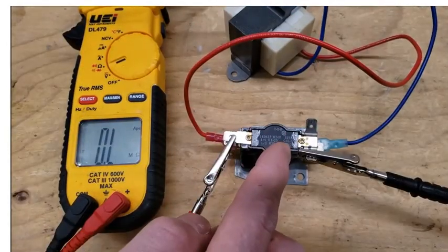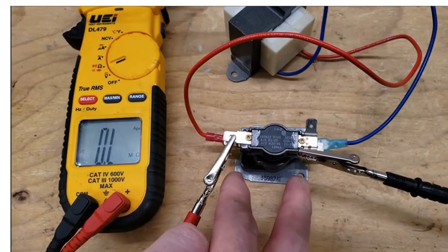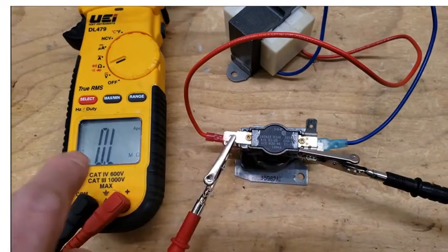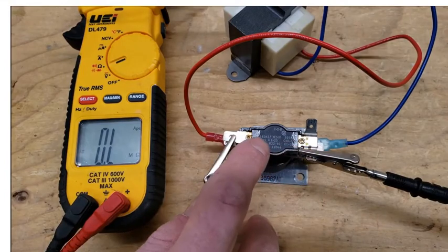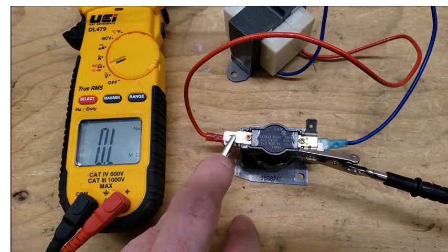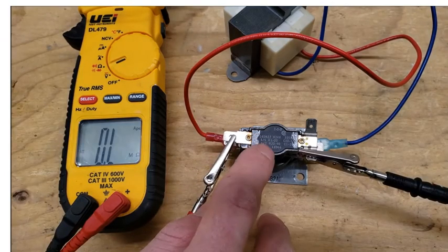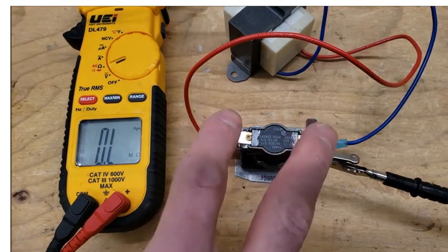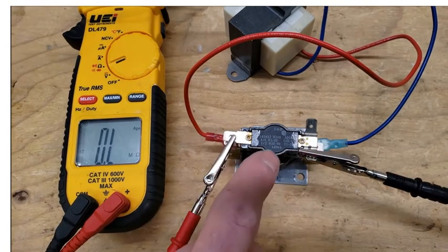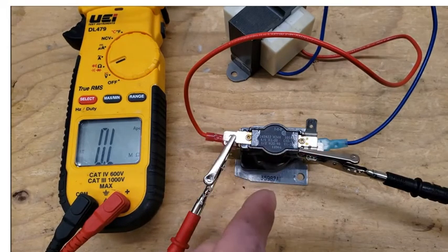So right now the sequencer is not powered. We're going to go ahead and power it again with 24 volts. We're going to read 0.0 ohms of resistance after the allotted time requirement, and this one is 1 to 20 seconds. But then after that I'm going to switch the probes down to the lower level, and that one is supposed to close between 30 and 90 seconds. So you're going to notice that they're not going to both close at the same time. You have to follow these time requirements, and that's because the rod is slightly offset from the other one when it's sitting on top of the bimetal disc.